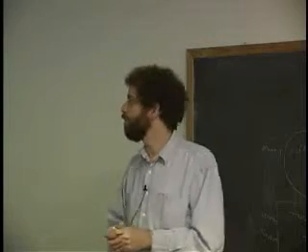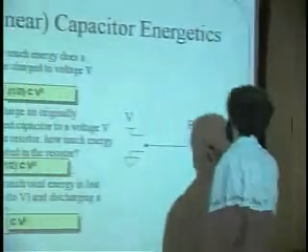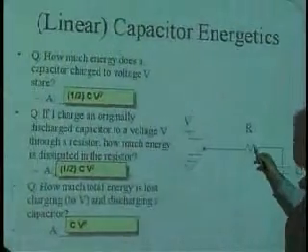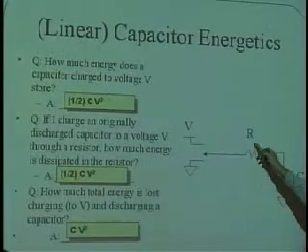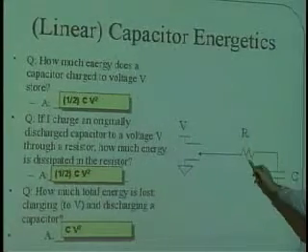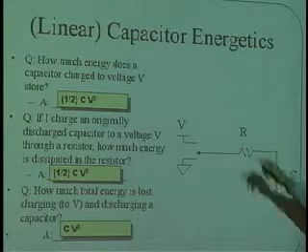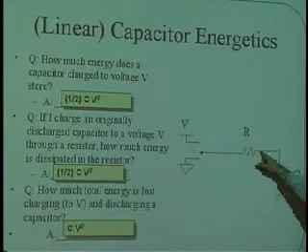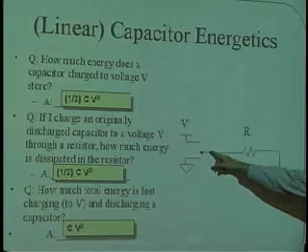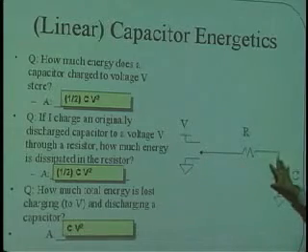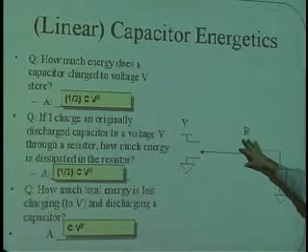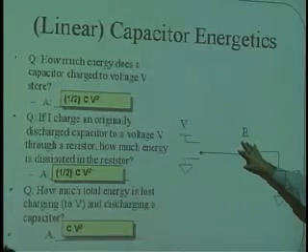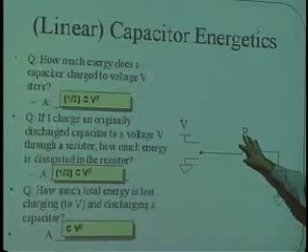Yeah. So here, the heat is dissipated in the resistor, because any current that's going through the resistor dissipates power with a law which is I squared R. That's the amount of heat loss, of power loss that's going through the resistor. So charging the capacitor up from a voltage source like this means that you do fill this guy up with 1/2 CV squared, but you also, in the process, dissipate 1/2 CV squared of energy in heat in the resistor trying to charge it up.